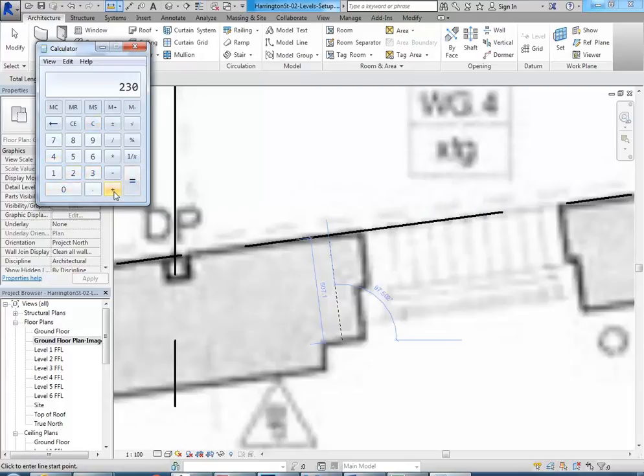They actually just did extra thick brick walls quite often before reinforced concrete. Yeah, that's right. So 230 plus 230 obviously is 460, and that leaves us with roughly a 50 mil cavity, which sounds about right. So 510 thickness for the wall is probably a good starting point.